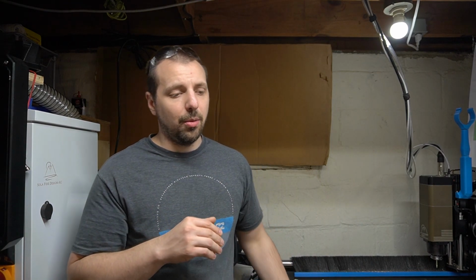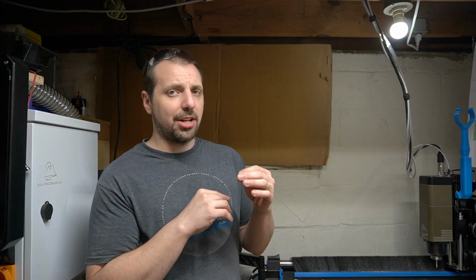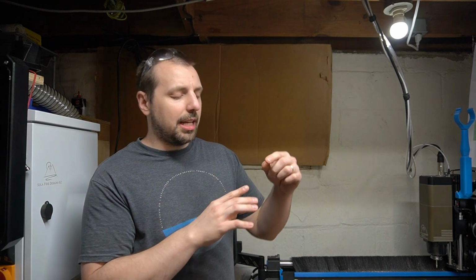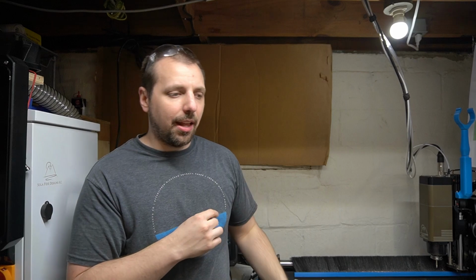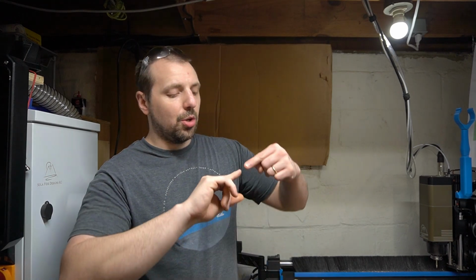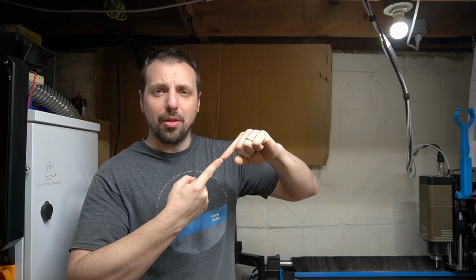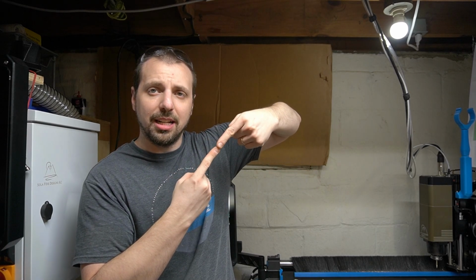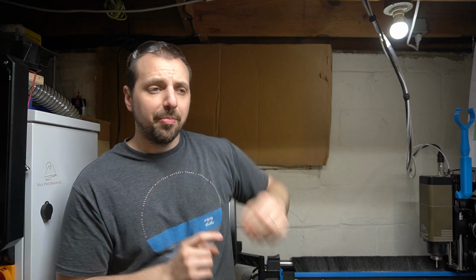So I know we're going to be using a Ginny bit for the roughing passes, and I know it's a compression bit, and the one downside to using a compression bit for any type of roughing is that where the up shear meets the down shear, you can get a line. And the same thing goes for when you're cutting a ton of material out. If you're cutting MDF, or plywood, or a solid piece of material in one pass with a compression bit, you normally get this small line right where those two meet, because you have one cutting downwards and one cutting upwards. And so there is that line that you can get on material.